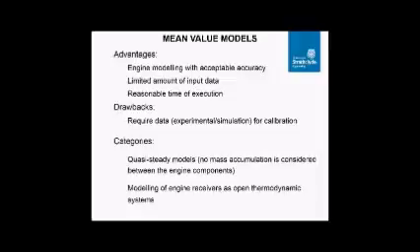For the mean value models, we have two categories. The first one are the quasi-steady models, where no mass accumulation is considered between the engine components. And then the second category, where the modeling of engine receivers is as open systems.